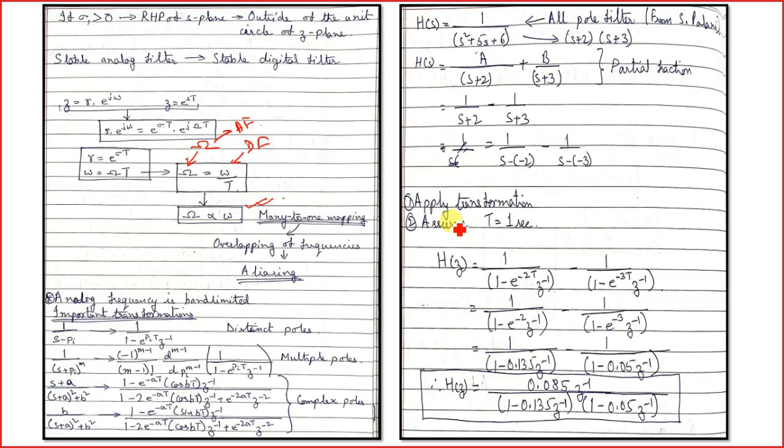Okay. And then we have discussed that due to this direct proportionality relationship, we have many to one mapping when we are using the impulse invariant method for the designing of IIR filters, right? So this is one of the major problems with the impulse invariance method. What is the disadvantage? The disadvantage is many to one mapping, and this results in aliasing.